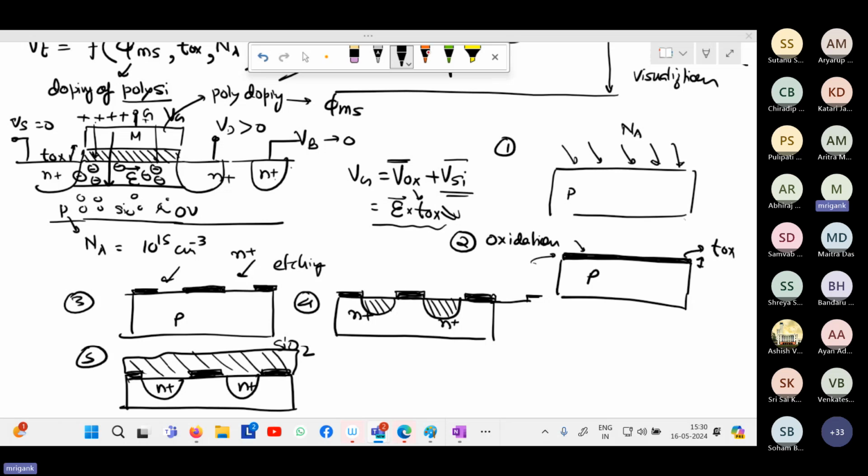This one. So in order to etch open now and create the contact, I will again etch these areas and deposit metal. So I can etch these areas and deposit metals so that I have the contact to this source drain region. So this red color thing that I'm showing is a metal layer. So you can have the metal contact going into the source and drain region through this field oxide. And then actually these are acting like wires, but ultimately these are like metal layers. And this is like the via. We call this term via.